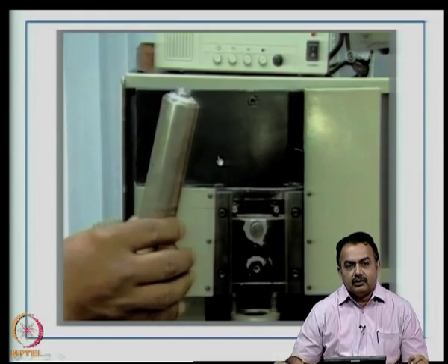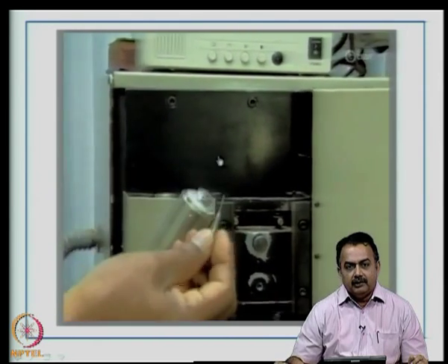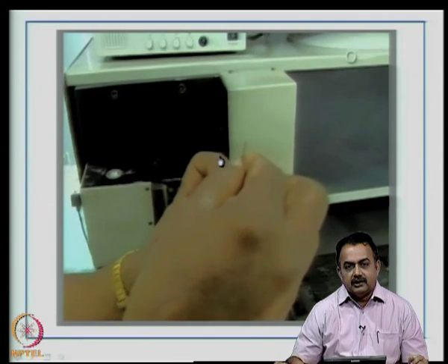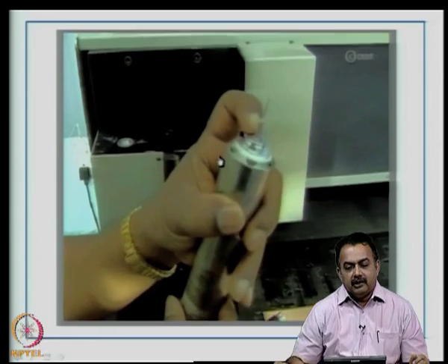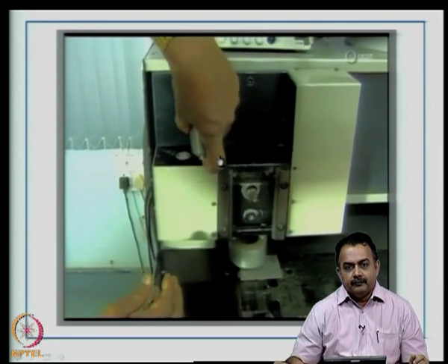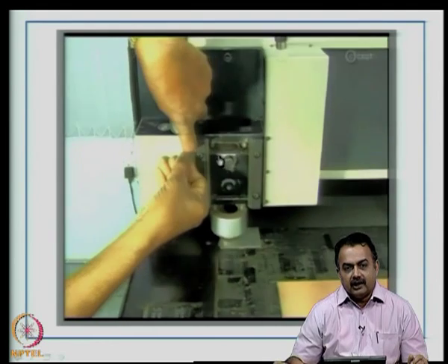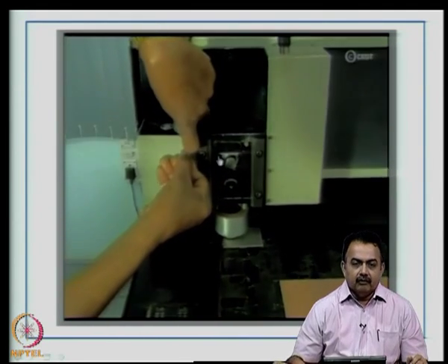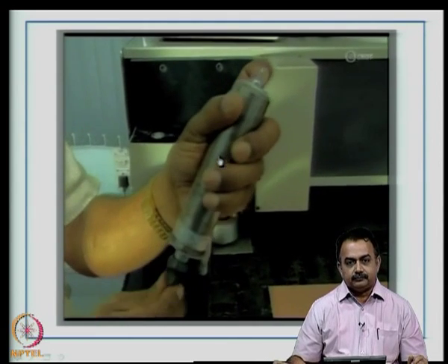Here what we are showing you is the spindle where you are mounting the drill bit. So, there are certain set procedures, especially with regard to the drill bit material protruding out of the spindle. Here the technician is showing you what kind of distance or height is required for a stack of, let us say, 3 laminates to be drilled through and through.